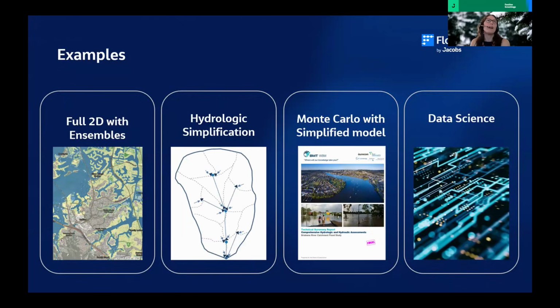The full range of scenarios are then simulated in the hydrologic model, which is typically a lot faster and less prone to issues with running. And the event producing the critical flow or level at the location of interest is selected for simulation in the hydraulic model. I've used this recently on a concept design of a bridge duplication on a very small waterway.